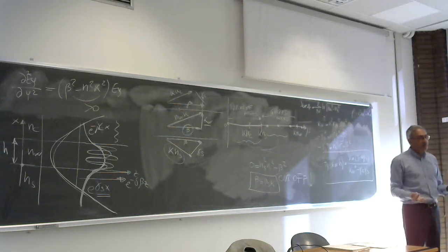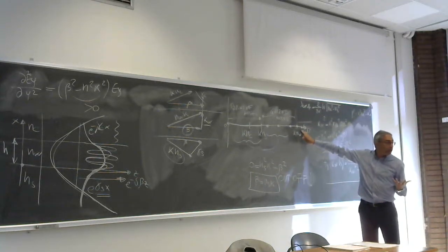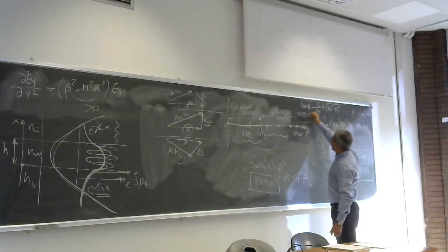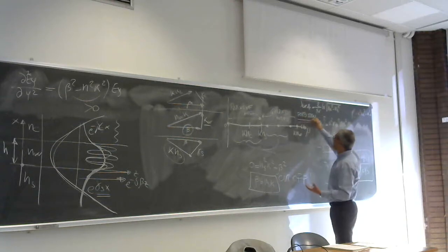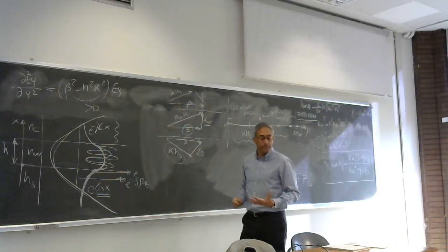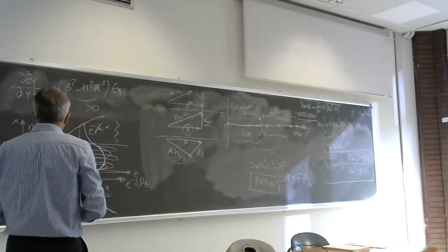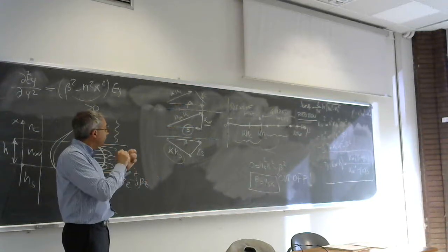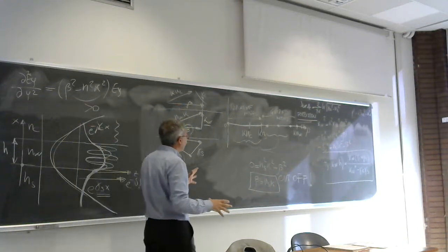Does it make sense physically? Mathematically, yes, so we have a solution here. But physically, no. It's not possible to have this solution. So this is a forbidden region, physically forbidden, and there are no solutions there. It is not possible to excite the mode, put the power, or put a shape of the field with the beta in this part.